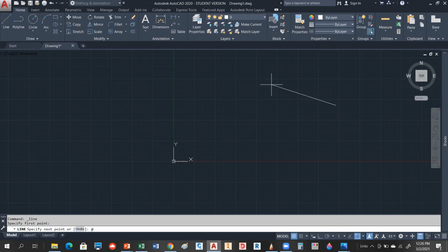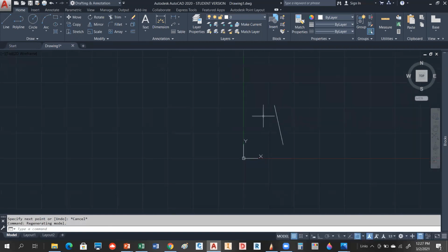Let's say we measured 100 feet, so I'm going to put 100.00, less than. This one is a north 12 degrees. Notice there's no degree symbol on the keyboard, so you have to remember the D, either uppercase or lowercase. I think it was 30 minutes and 00 seconds, and then you're going to be west. So I would enter that, and notice that puts me like that.